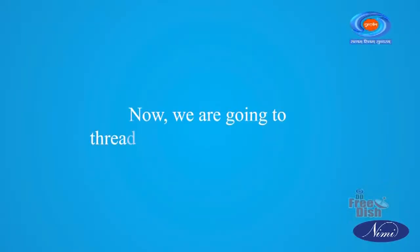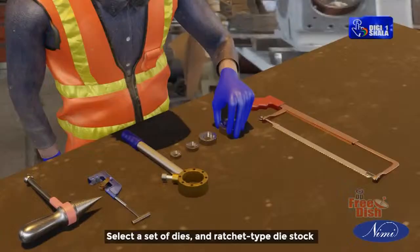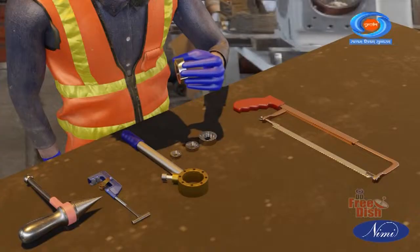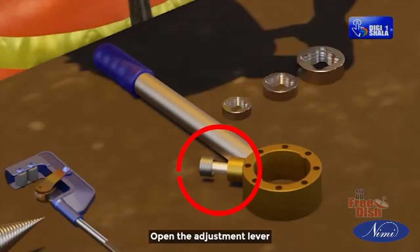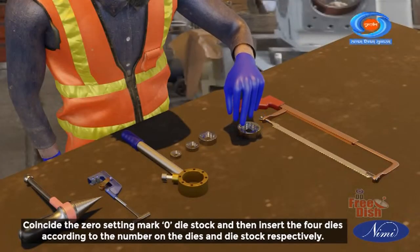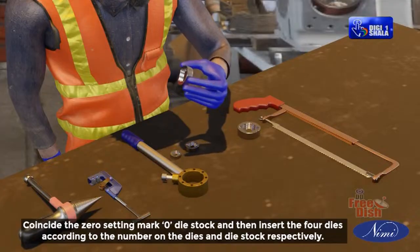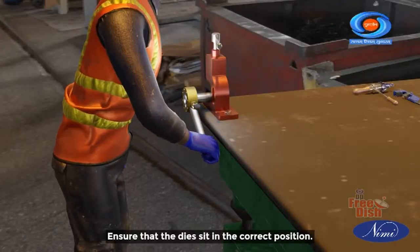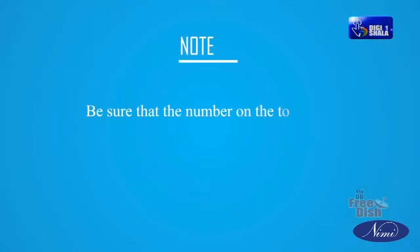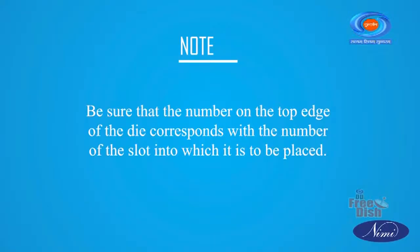Now, we are going to thread GI pipes using die stocks. Select a set of dies and ratchet type die stock. Open the adjustment lever, coincide the 0 setting mark on the die stock, and then insert the 4 dies according to the number on the dies and die stock respectively. Ensure that the dies sit in the correct position. Note: be sure that the number on the top edge of the die corresponds with the number of the slot into which it is to be placed.